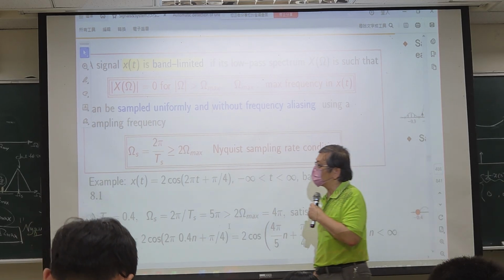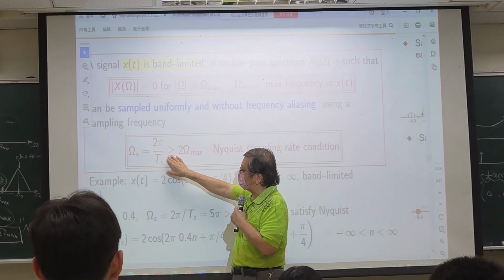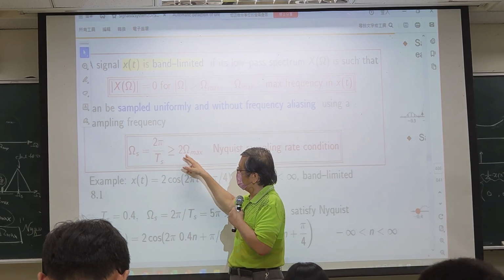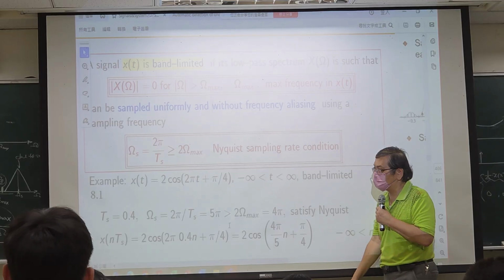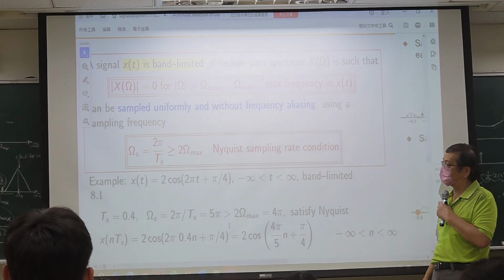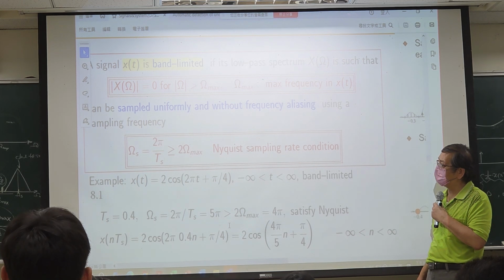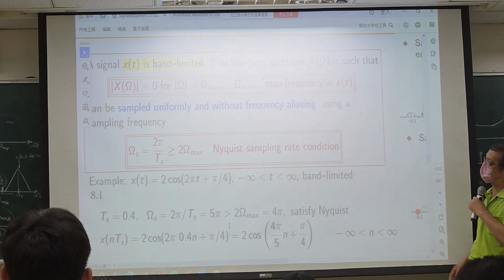Okay, so again, your sampling frequency must be greater than, I don't want to use equal, must be greater than 2 times the maximum frequency component of your signal. Okay? And that's called the Nyquist sampling theory, the Nyquist sampling rate.